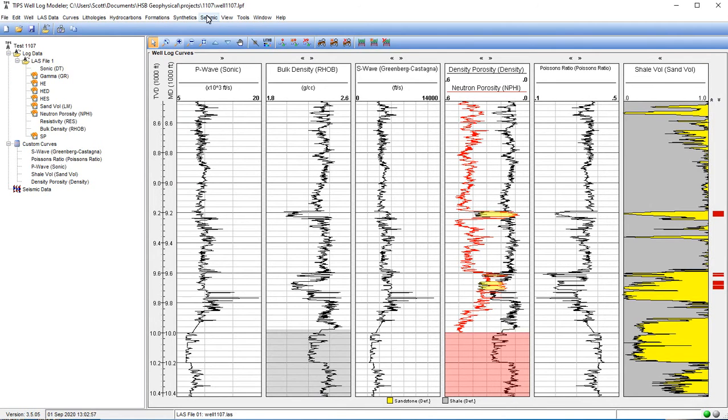In the past, we would click that and you would pick a single seismic line that was associated with this well. Now we actually have the ability to put in multiple seismic lines to do our well ties. And so we can click the button at the top and hit seismic, add seismic line, and that would show it down here under this node in the tree.